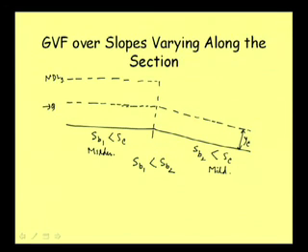And now, if we just try to recall our discussion, here also normal depth will be in the channel 2 also, the normal depth will be above critical depth because these are mild slope, but the normal depth line in channel 2 will be less than the normal depth line in channel portion 1.